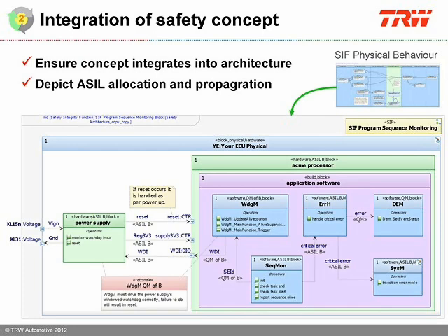The flows that cross the swim lane boundaries on the SIF's activity diagram identify the interactions or interface flows between the physical blocks. Some flows may already exist, others are created as required. The flows are also used to specify the input and output parameters of the physical operations that represent the physical activities. An internal block diagram is used to depict the flows between the physical blocks. The SIF has now been integrated into the overall physical architecture of the ECU.